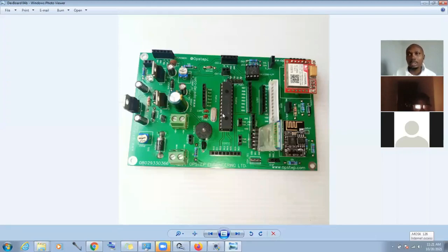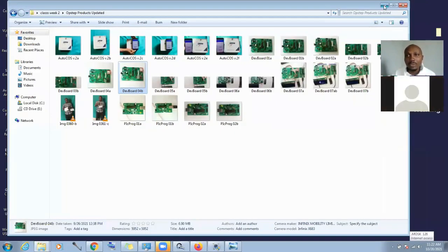And for those who already have it, the IC on this board is the PIC 16F876A. The oscillator there is 20 megahertz, and the ceramic capacitors are 22 picofarad. So that is actually what I'm basing the circuit diagram I'm drawing on, because this is where we are eventually going to flash the code in. Okay. All right, I just needed to say that.